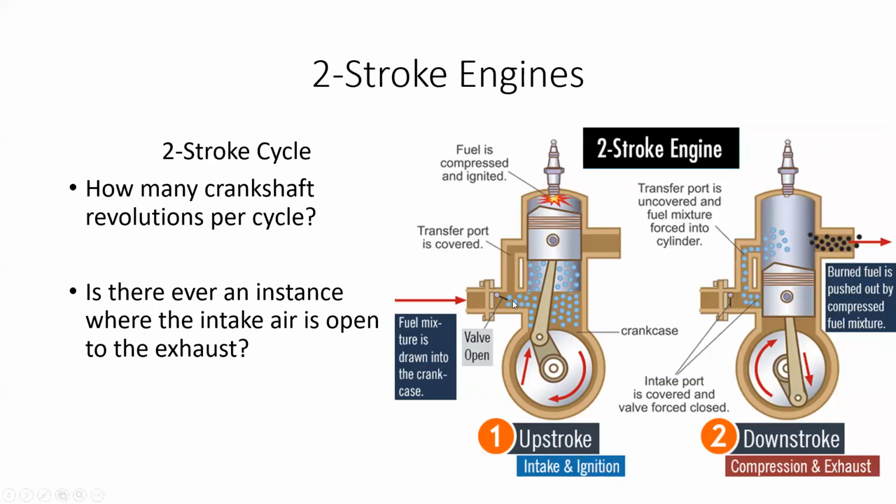So with a two-stroke engine, you mix the oil into the gasoline. That's another big reason why these things pollute so much: every time we have the ignition, we're not only burning gasoline, but we're burning oil as well. And burning oil pollutes a lot, right? That's why when you see a two-stroke engine, if you're familiar with those at all, you see blue smoke coming out of them. Even when they're running well, they're burning oil, so they smoke quite a bit, and that's really why they pollute so much.